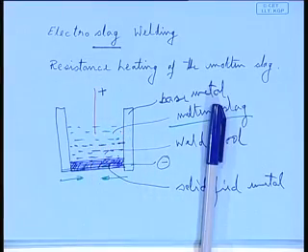Theoretically, only that much, but in that case you do not need to put extra flux during the welding process. For example, in any other welding, say gas metal arc welding, you will have to continuously inject CO2 or argon or helium. When you are doing submerged arc welding, through the hopper you will have to continuously pour flux. Once the welding is over, the flux lying on top of the slag, which is not melted, you recycle back, but the rest has got burnt, you have to throw that. Again, when you do the next plate, you have to add additional flux. Flux is getting consumed. Here flux is not getting consumed. What you have started with continues through the whole process.